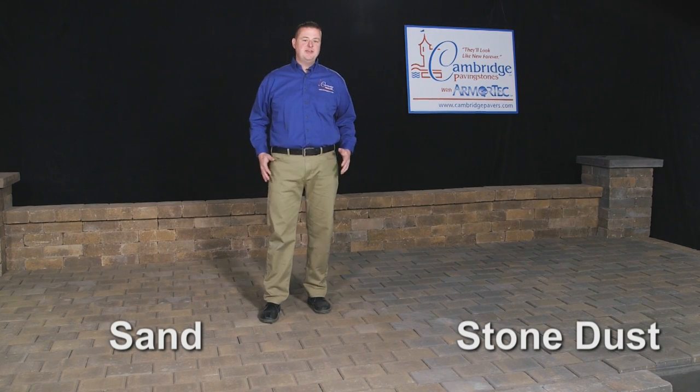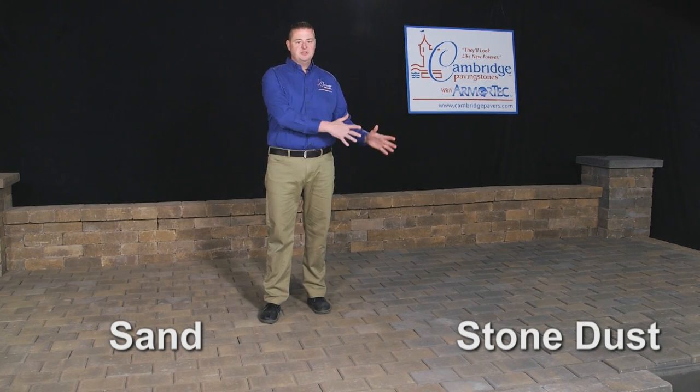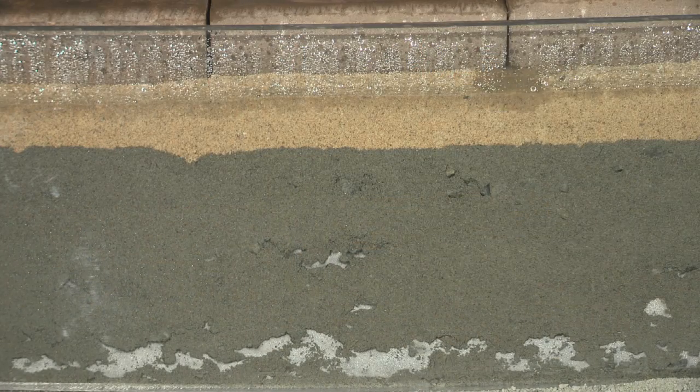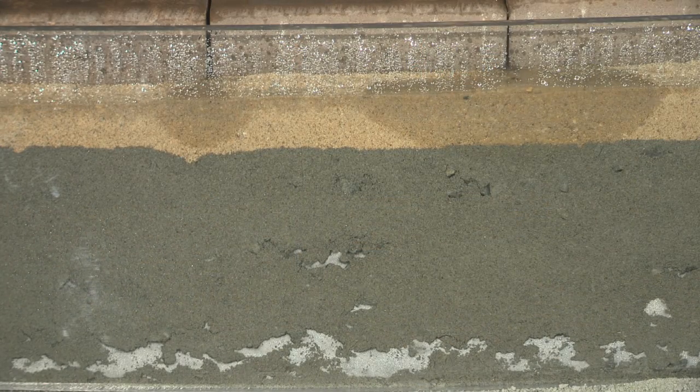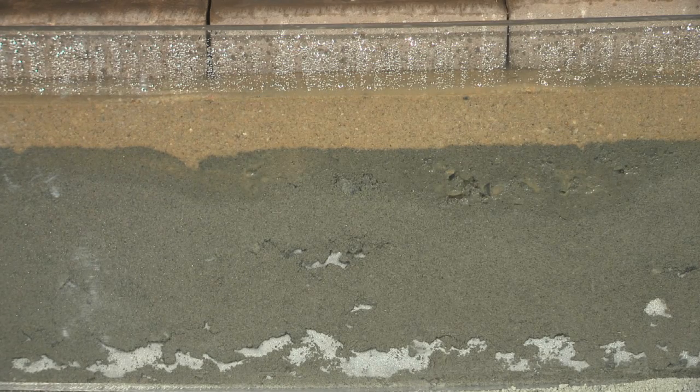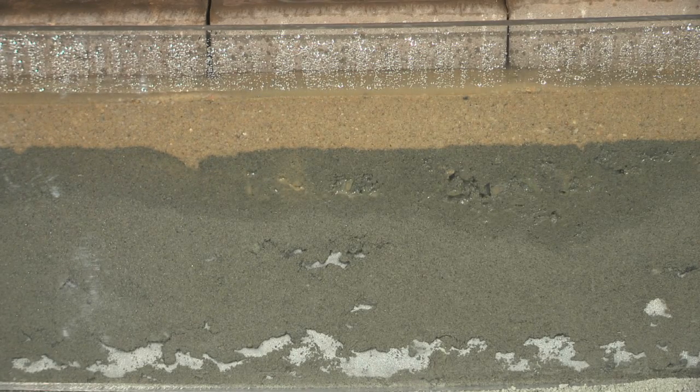Here we have two identical installations. One is on stone dust, one is on sand. For demonstration purposes, we have not used polymeric sand in the joints. As we introduce water onto the installation to simulate a rain event, you will see how water moves freely through the sand setting course and drains off the installation. The side with the stone dust retains water as the fine particles in the stone dust act like a sponge, retaining water under the pavers.